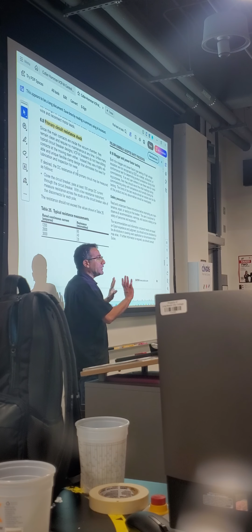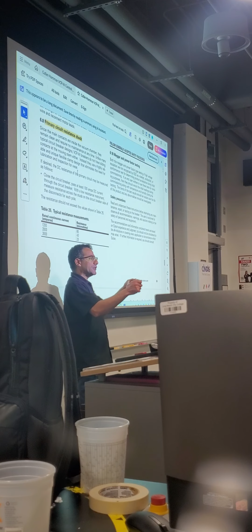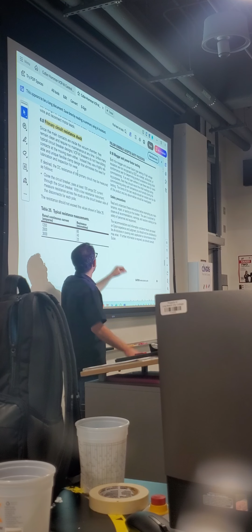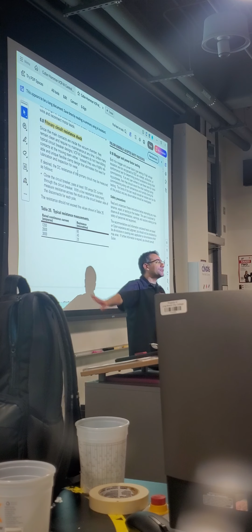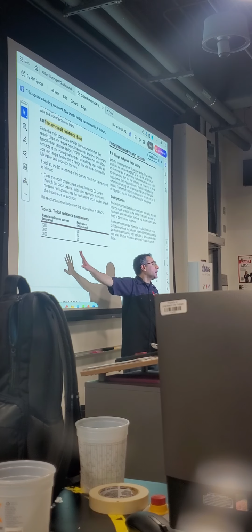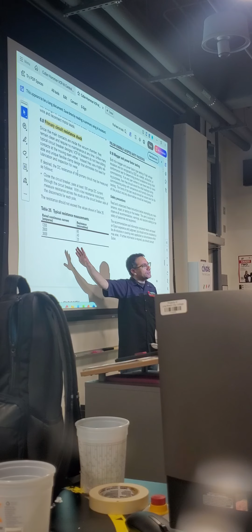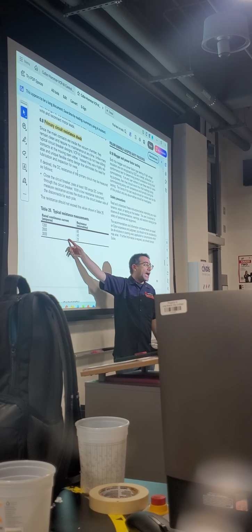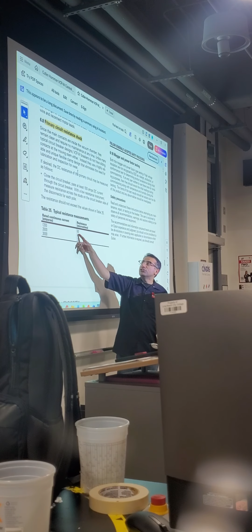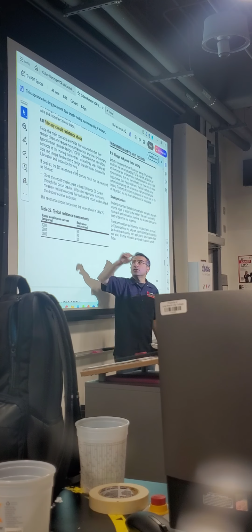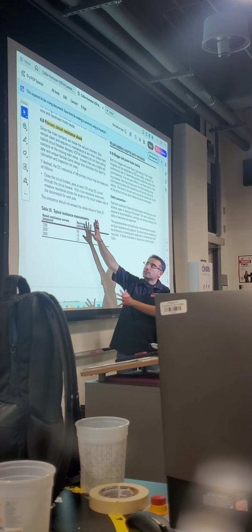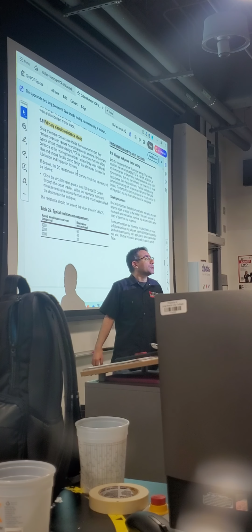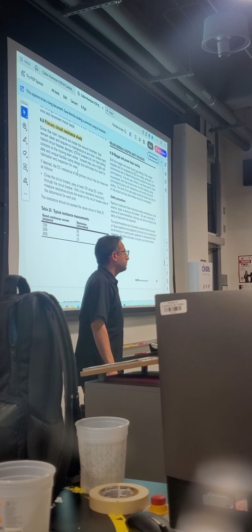So they are not talking about the 50% rule. They are saying measure all three phases. As long as all of them are below 60 microohms, you're good. So that's what we are referring to, the manufacturer document. In the absence of a manufacturer document, go with the 50% rule. But here we have it. So did you have any reading above 60 microohms? Yeah. So based on this criteria, it failed. So that's the proper way to test it.